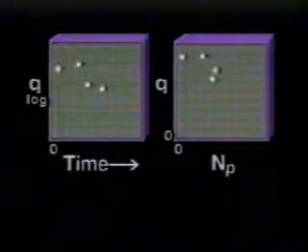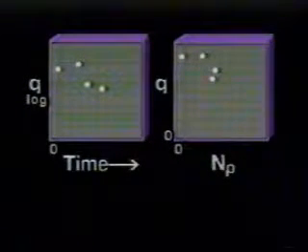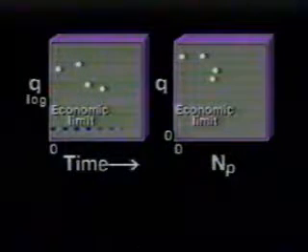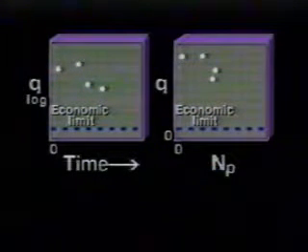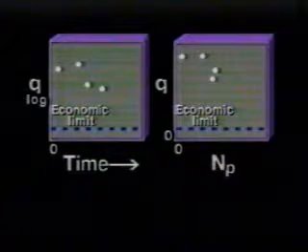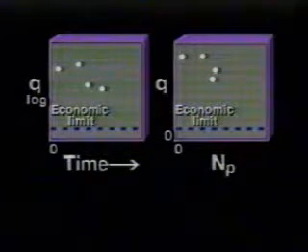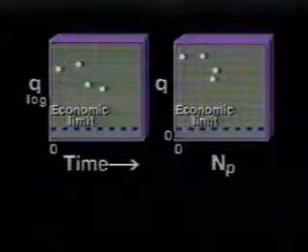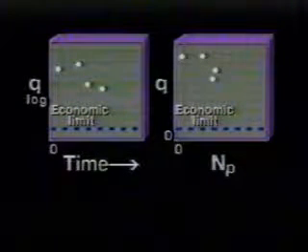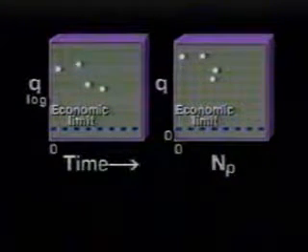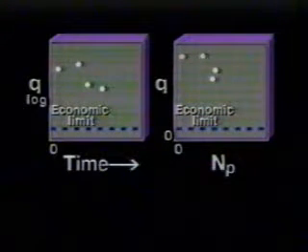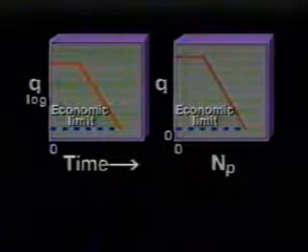Next, we smooth the data, or find the best straight line for the points given, and calculate the economic limit production rate. Before proceeding further, we check to be sure that no new operating practice has been recently imposed or will be imposed in the near future. Satisfying ourselves on this point, we are then free to draw the straight lines on the two plots.